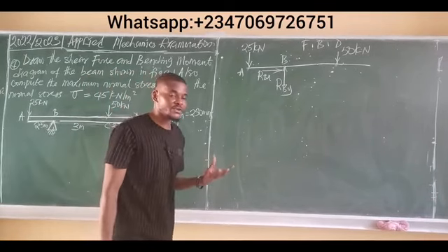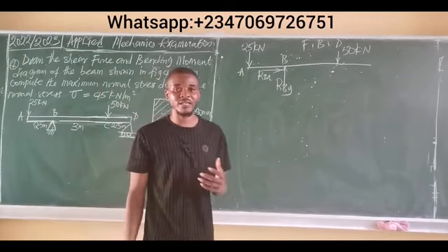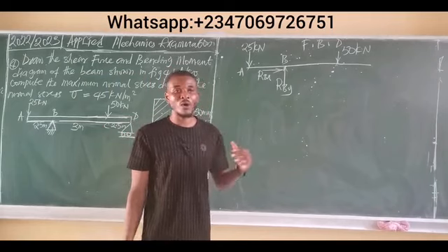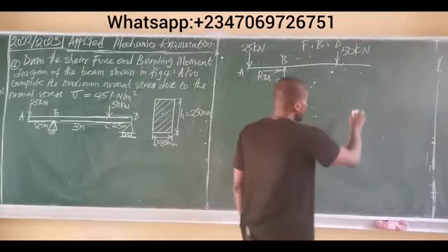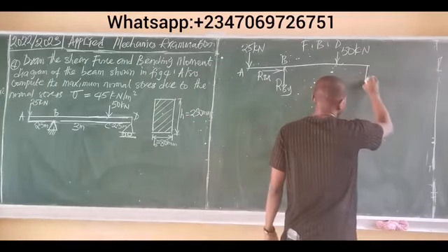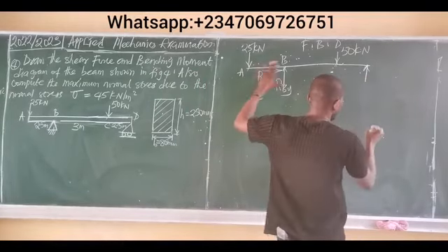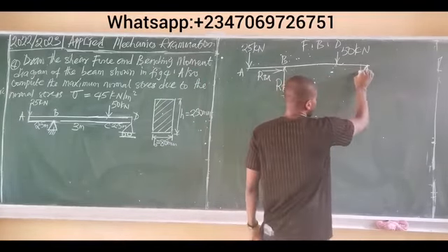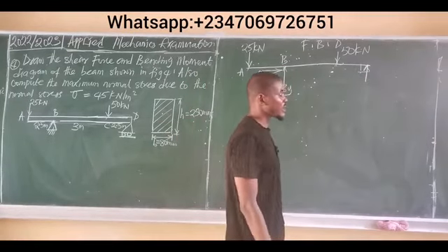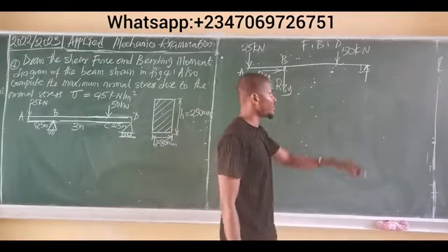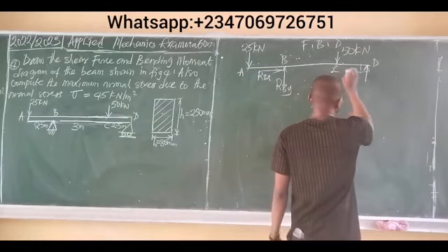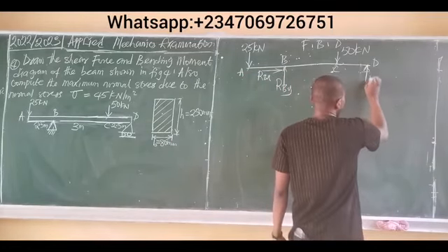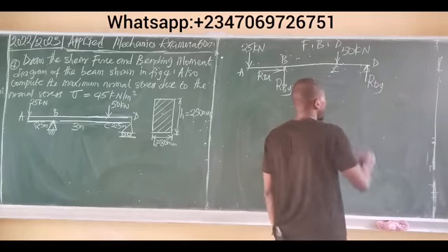And I've said in my videos on shear force and bending moment analysis that whenever a roller occurs on a horizontal beam, then it simply has a vertical reaction. So you can have something like this. Seeing this beam is a horizontal beam, automatically this is a vertical reaction because it makes an angle of 90 degrees with the beam itself or the point of occurrence. So this is point D, this is point C. We simply call this RDY.